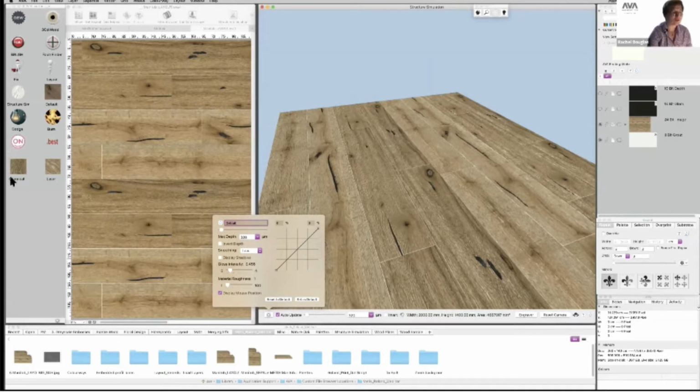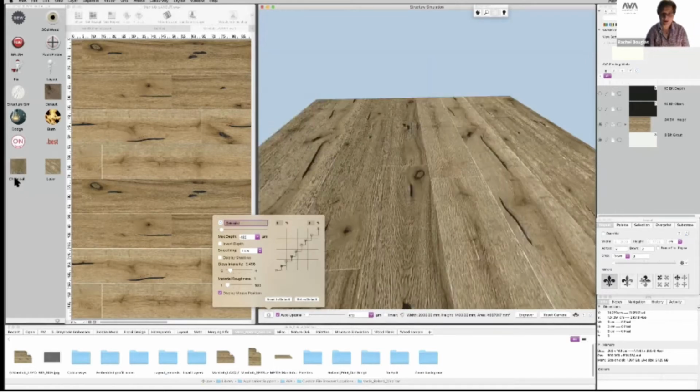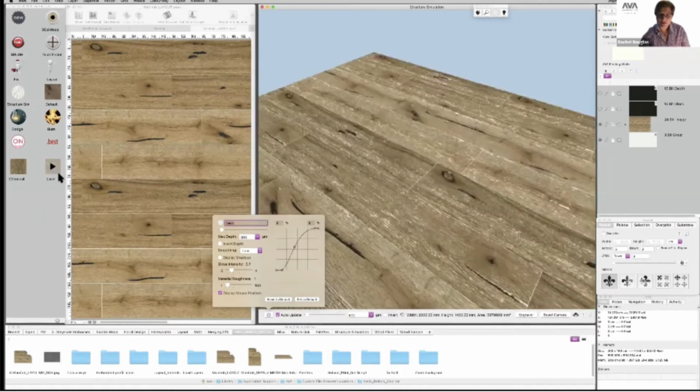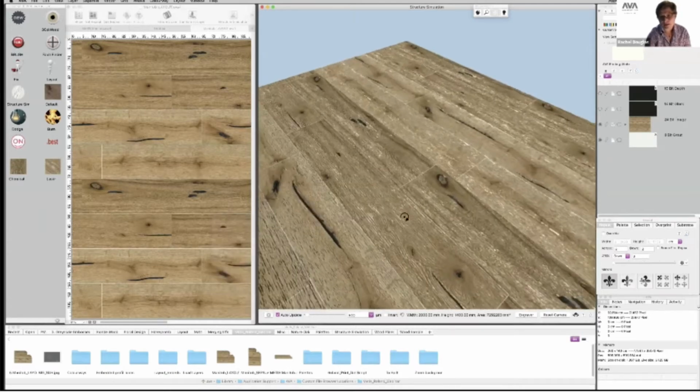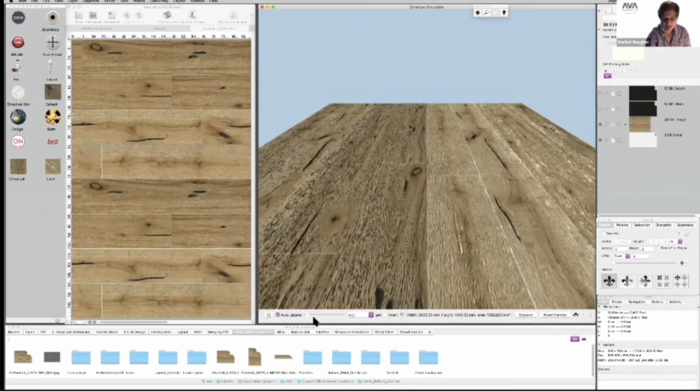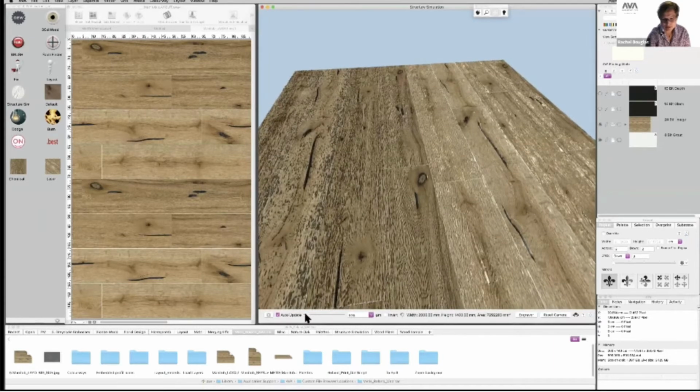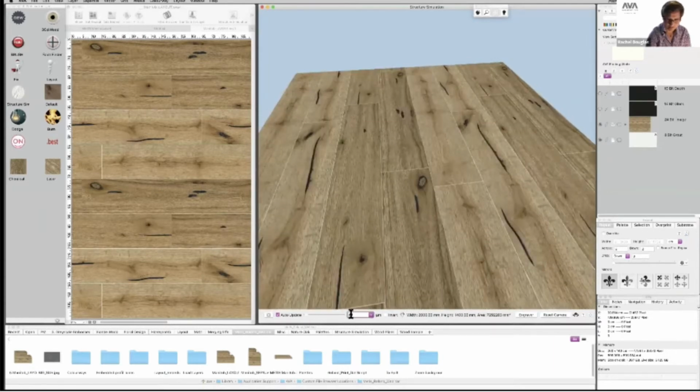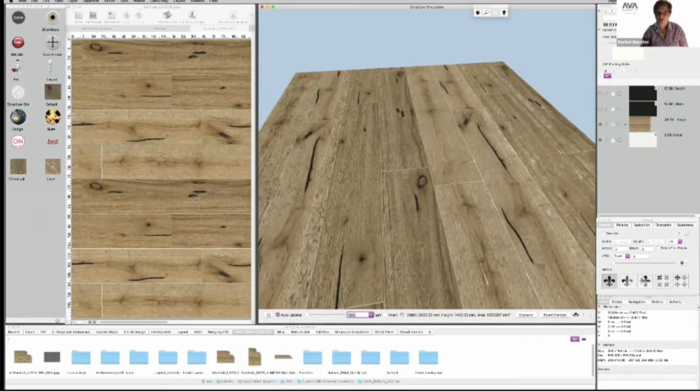So I have two saved versions over here. I've got a chemical emboss, so I can apply that, and I've saved it with a preset angle, if you like. And then I've got a laser one. So again, you can see the curves change here, the gloss intensity changes a little bit, but I can still spin that around and I can change the microns down here to reflect the amount that it's going to be engraved at, so that's 300.